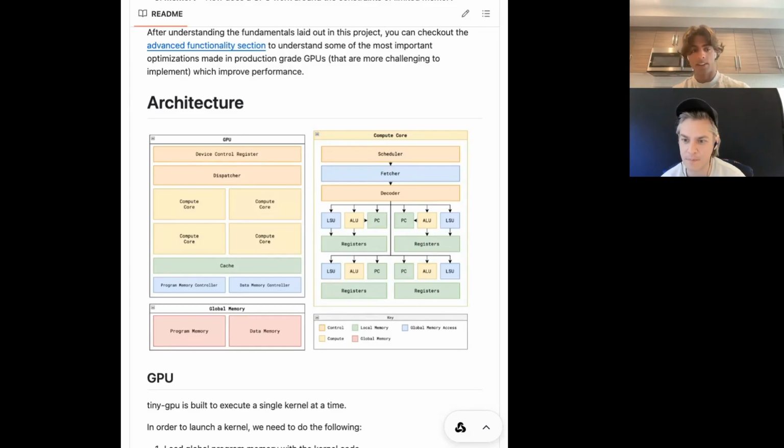Yeah, definitely. So I think most people doing architecture and design, they'll probably understand most of these elements at a gate level. Obviously, for more complicated logic, it's futile and there's no point really to try to understand exactly what's happening at a gate level. I think the main intuition you need is to understand the core of how memory works at a gate level, usually like static RAM. And that's pretty interesting. You understand how a latch works and then a flip-flop works. And that's the core of understanding memory. In practice nowadays, most memory is dynamic and only cache is static. But that's something people understand at a low level. And then ALUs, and again, we're going to go into the diagram and that's going to show you basically as close to the low level as you get.